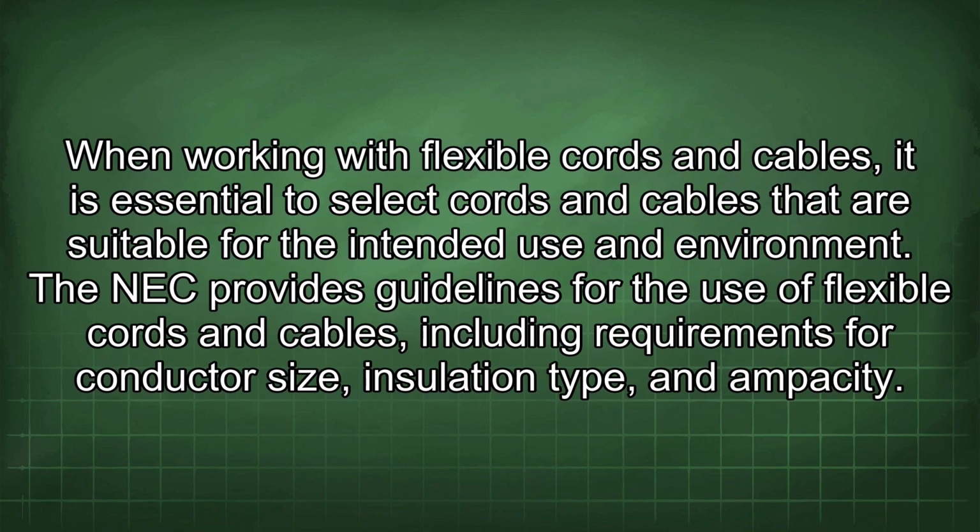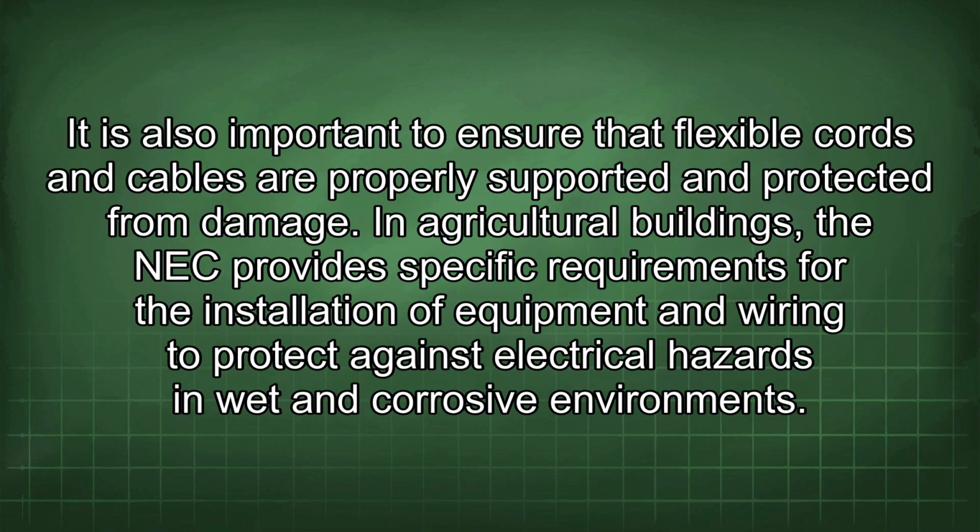When working with flexible cords and cables, it is essential to select cords and cables that are suitable for the intended use and environment. The NEC provides guidelines for the use of flexible cords and cables, including requirements for conductor size, insulation type, and ampacity. It is also important to ensure that flexible cords and cables are properly supported and protected from damage.